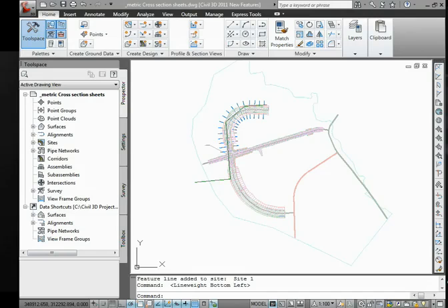In Civil 3D 2011, the process of generating cross-section sheets has been simplified. Layouts for plotting cross-sections are created using a cross-section view wizard. Cross-section sheets are then created via the Plan Production feature. Cross-section sheets will be included in the plan document package for this project.